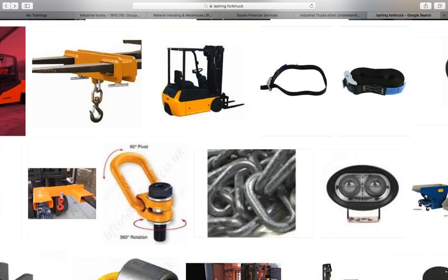What happens with those outriggers, for anybody who's not familiar, is they have hydraulics that go down and lift the vehicle, and they also have hydraulics that push out. So they will push that outrigger out depending on where the manufacturer tells them to set it, depending on the load or the weight. Often they may tell them to push them all the way out, or if the operator is not certain or it's not specified, you always go all the way out on those outriggers.